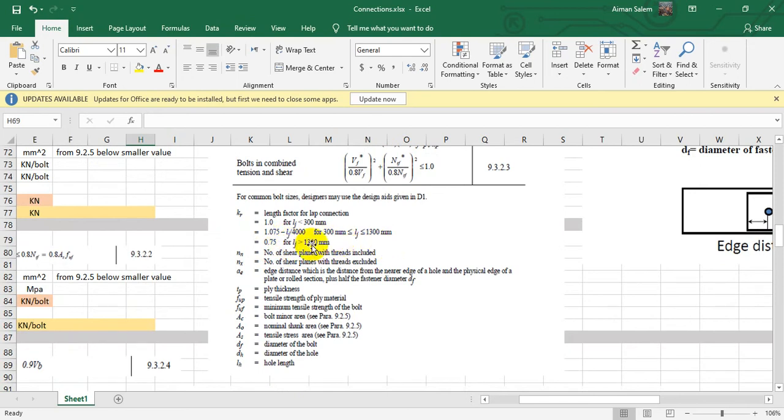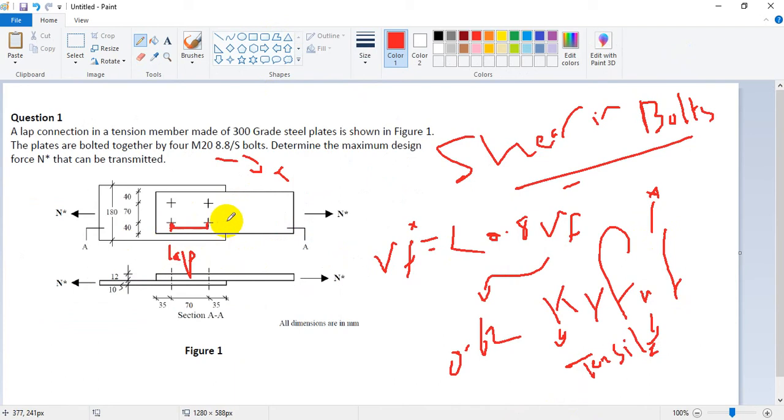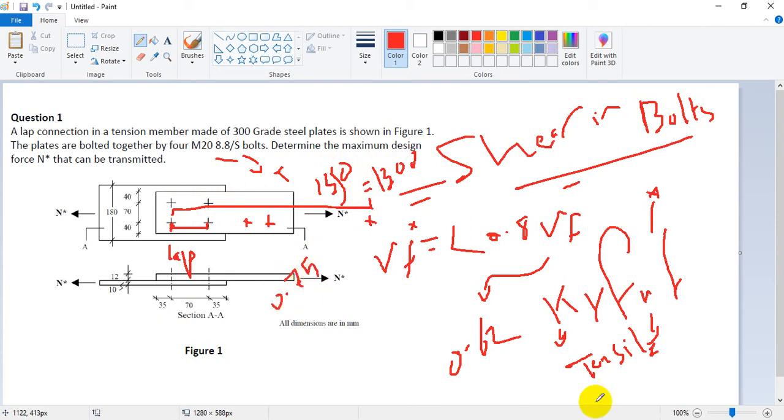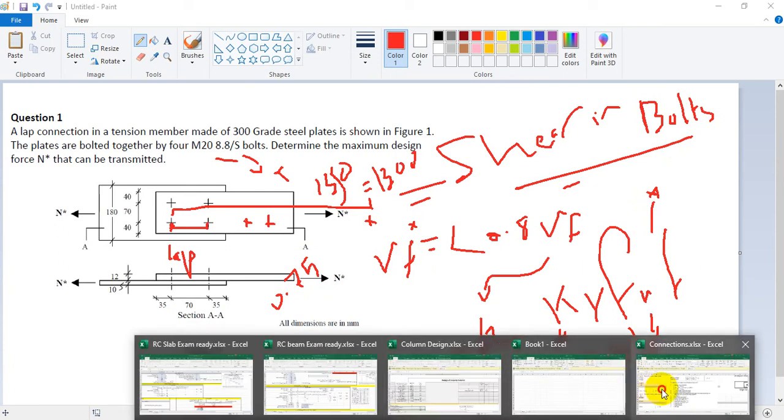So this is actually if you have 1400, something like that, between the first and the last bolt, as I've already shown. So for example, if you're having more bolts here, more bolts here, and then you calculate this is the last bolt, you calculate the distance from here till here, and you find that okay, this is actually 1350, which is more than 1300, which goes to the third, so KR is going to be 0.75. So this is how you basically do it.